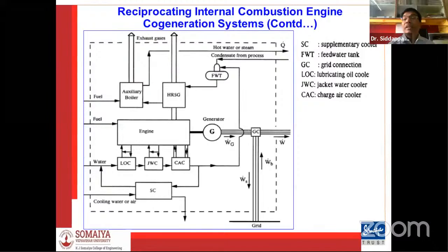The only thing we can do is increase the enthalpy of the system. Therefore, in gas turbine power plants as well as in steam turbine power plants, we use a concept called reheating, or staging of the steam turbine or gas turbine. Staging means we are just adding external heat to the system at the pressure at which the gas is available to us. You can use that concept here also in any IC engine.